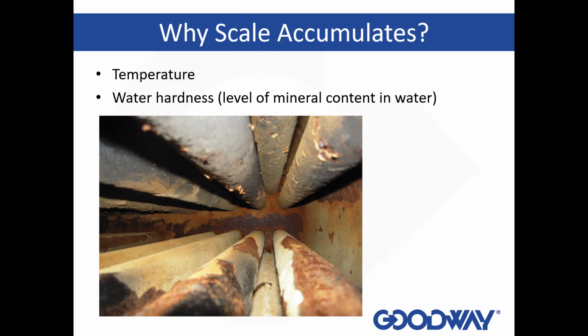So when you have water in the tea kettle, you've got the burner underneath it, and you're evaporating off the water, and only pure water will evaporate. It leaves behind all of the dissolved solids or the minerals that are in the water, and they end up plating out. Now, that is basically a good analogy to what's really happening in a Firetube boiler.